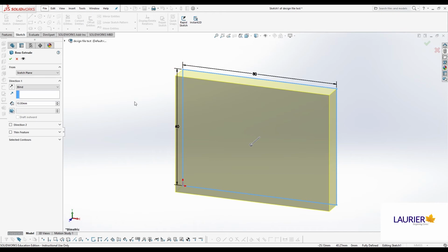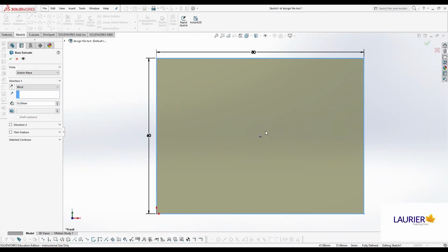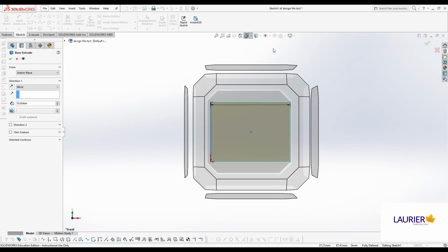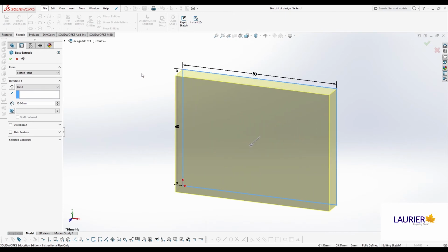The very first time you go into 2D, it'll flip it so that you're looking at the 2-dimensional plane that you're drawing on from a normal view, straight down on it. And when you come back to 3D, it's going to put it on a nice oblique angle on you. And it's just kind of recommending this. From now on, you're on your own. You have to manually reorient the part if you need to look at it from a different angle to do some work.